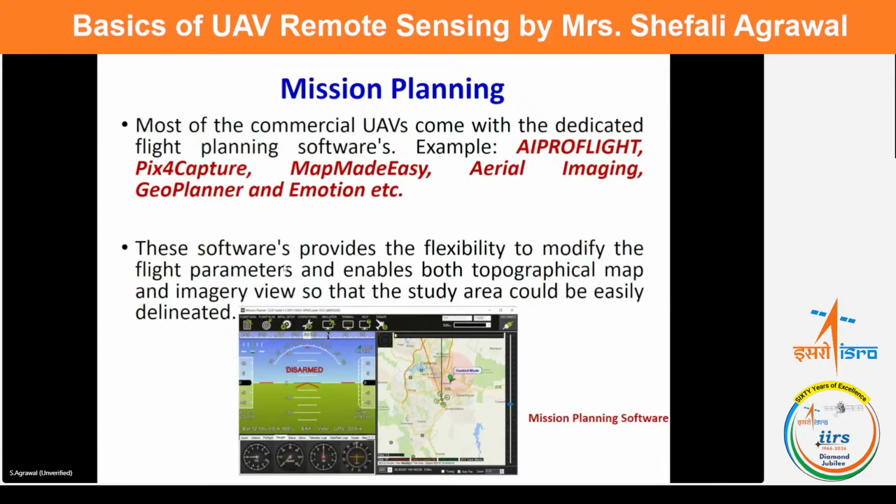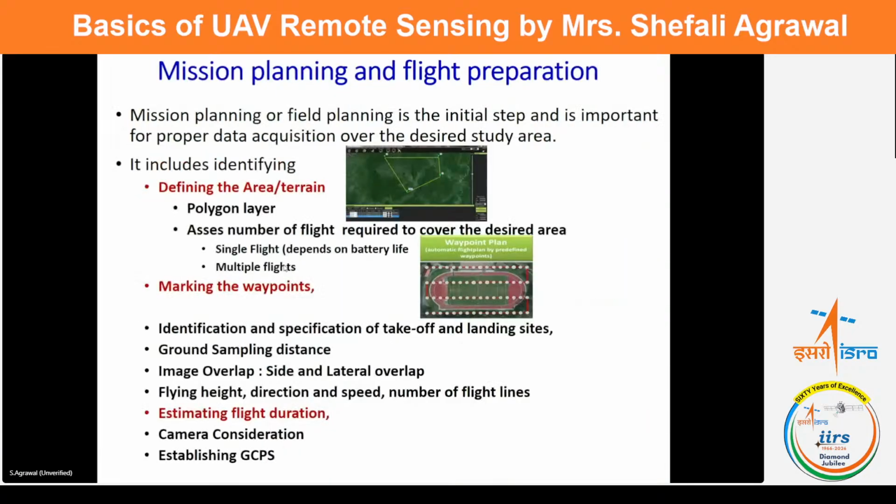And even if you buy a drone, along with it, they give you mission planning software. So ensure that you have this software to plan the entire data collection strategy based on which you will collect the data, because if it is not correctly planned, then the data acquired may not be of proper use.